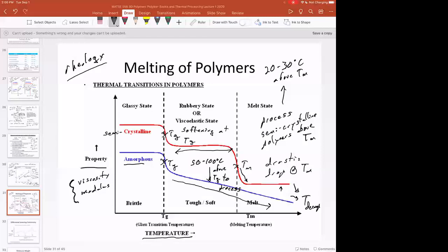And it just really depends on the chemical structure, because when you're decomposing a polymer, that is reliant more on the chemical bonds within the system rather than any intermolecular forces or anything else. TG and TM are really driven by intermolecular forces, where decomposition is driven by the intramolecular interactions or the covalent bonds. Okay, thank you. Great.